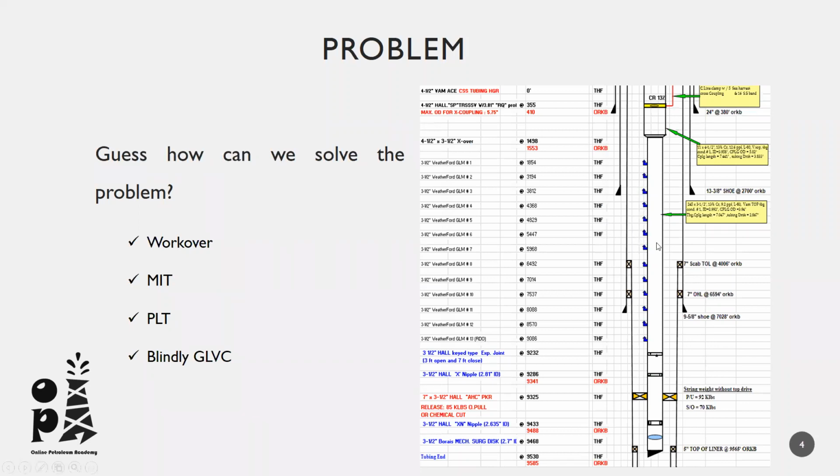Communication means there is a path between tubing and annulus in the reverse direction. So flow can go from tubing to the annulus. In offshore gas lifted wells, the normal pathway of the flow is injection gas going in the annulus side, then going inside the tubing. But if flow can go in the reverse direction, this well can be a high risk well because there is no control of flow in the annulus side, because there is no surface safety valve inside the annulus.